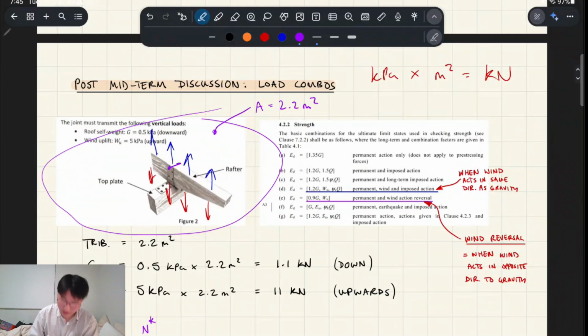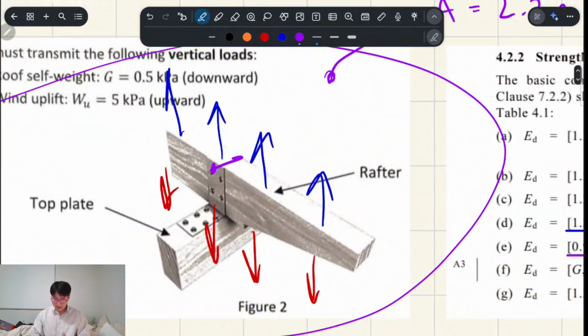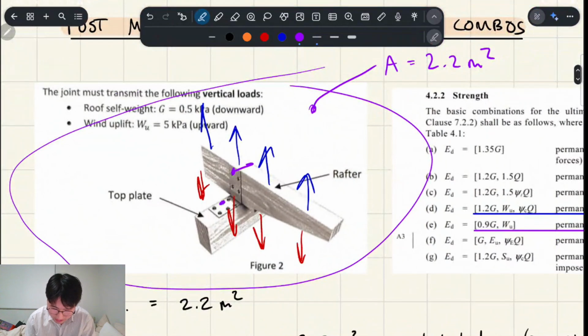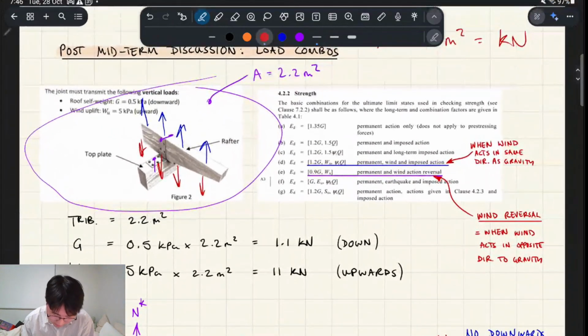So for these connections, correct me if I'm wrong, but type 1 connections were the shear ones. The bracket and the rafter would shear against each other, and try to split that screw in half, whereas these ones here on the top plate and that part of the angle bracket, that's being ripped up, so that's a type 2 screw happening there. So yeah, basically there's going to be some axial load here, and there's going to be some shear load here, right, from the same